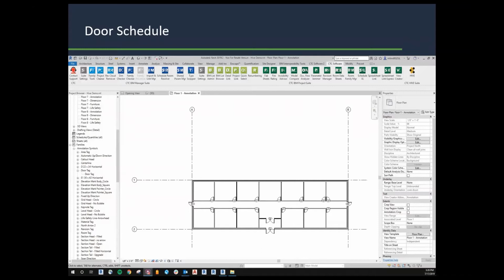And I challenge them to start developing schedules that bring more value to their client. You can tell them not just square footage, but you can get down into departmental level what kind of area they're looking at on the fly. You can give them rough costs on elements because Revit can track all of that if you've taken a few minutes to write a schedule for it.